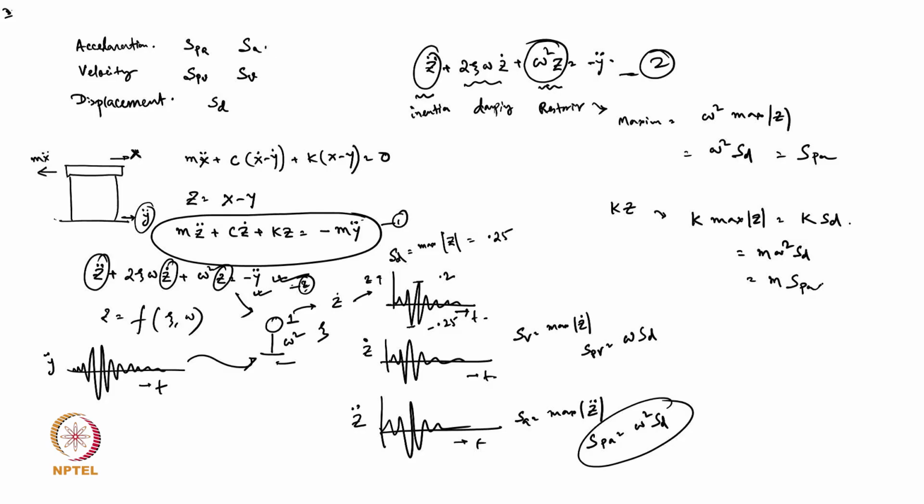So don't get confused. That is not at all spectral acceleration. That is pseudo spectral acceleration. Okay, that terminology is different, but they have written it clearly, that is pseudospectral acceleration, but they use the term SA. But in the structural dynamics context, we use this term as SPA. Okay, so don't get confused with that. That is also pseudospectral acceleration, and all the codes, ASCE, ACI, I don't think ACI has that, ASCE, Euro, all those codes have the same SPA concept. They all are giving the SPA, no other values. Okay,